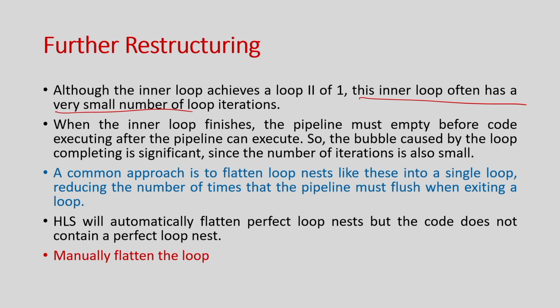So, this does not give you much benefit from pipelining, right. Even if I apply pipeline and achieve II equal to 1, this may not be the best design, it does not give you much performance benefit. And there is another problem: once you apply pipeline, you have pipeline stages, and you have to flush the pipeline before you start the next iteration. Here, because I call this function often for smaller arrays, and my first call does not give any benefits, you need some clocks to flush the data, because otherwise the pipeline will calculate something wrong. So, you have to flush the data, and then call the next function. This adds some extra overhead of making it pipelined, although my pipeline is not giving benefits.